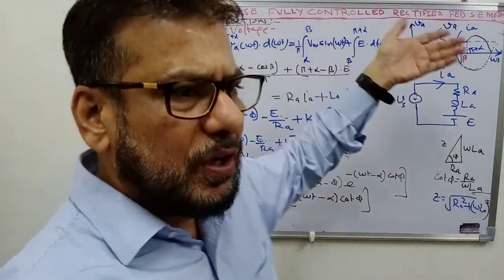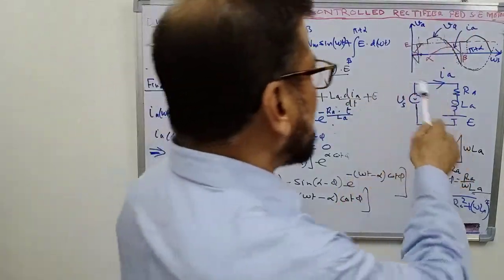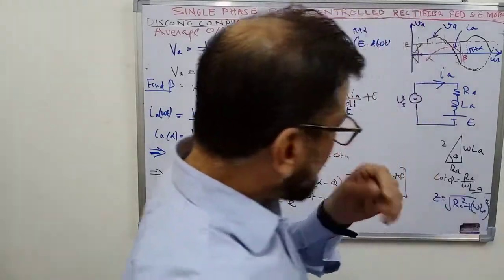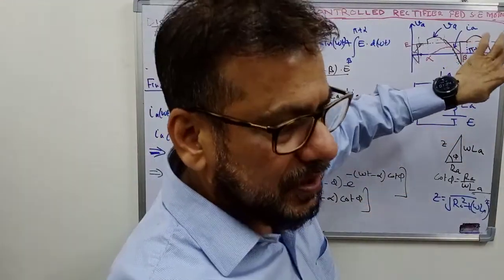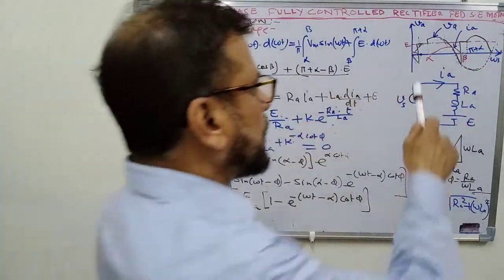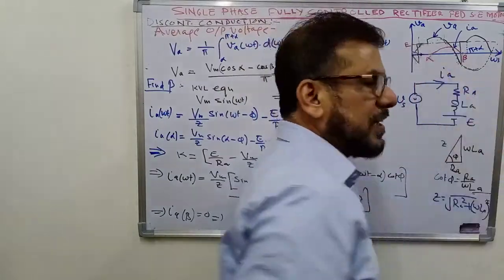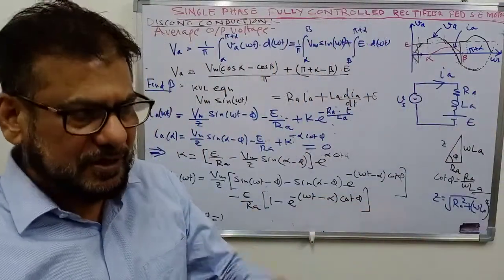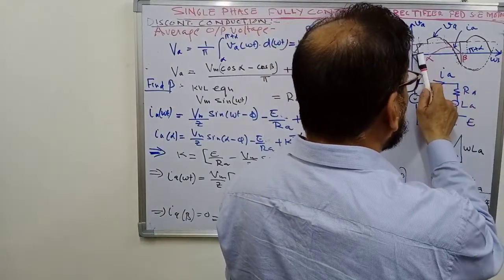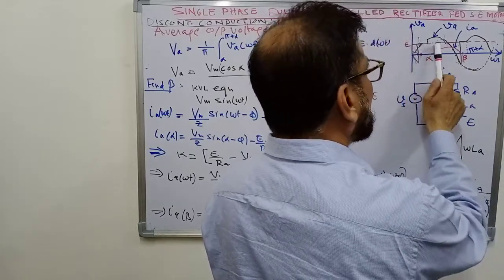So, you recall the previous lectures where we discussed the waveform in detail. We have seen that when the current falls to zero, the back EMF of the motor appears across the terminals of the motor, and the output voltage becomes equal to the back EMF. So this is the back EMF, which is slightly less than the average value of armature voltage. As soon as the current falls to zero, the output voltage VA becomes equal to E, that is the back EMF.